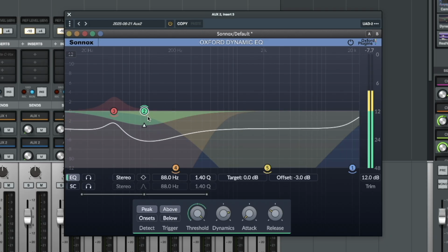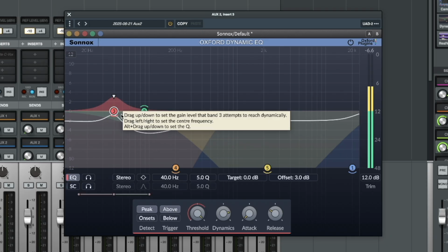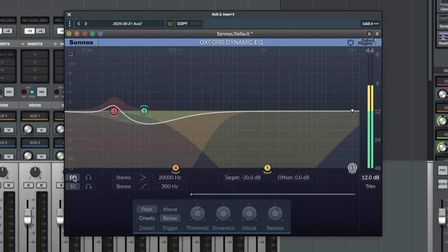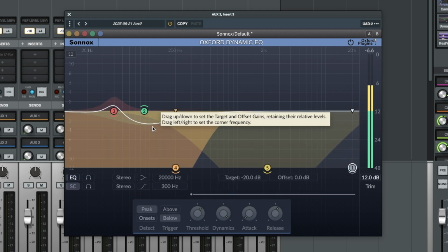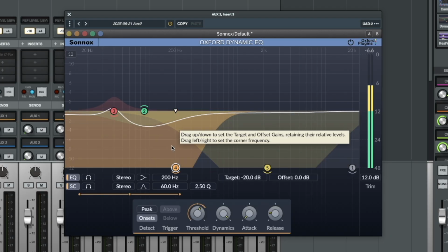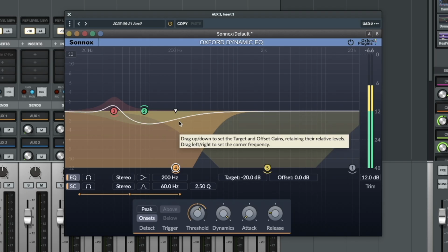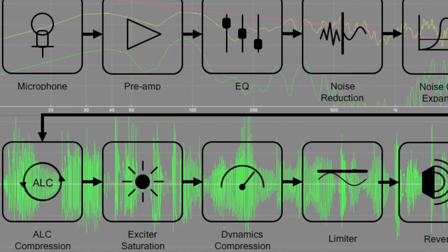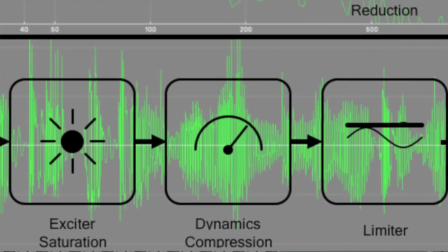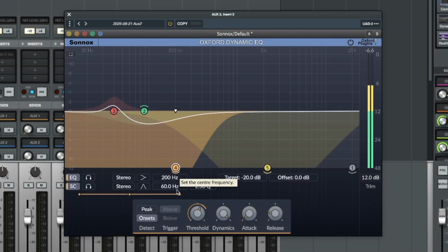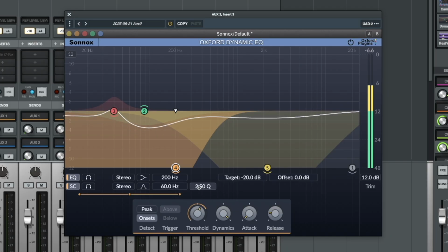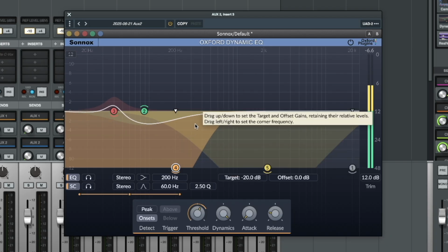Little bit of extra EQ I've decided to put in there. A little bump. Let me turn this off again, actually, so you can see that profile there all the time. And I've got this filter here, which is a de-plosive. Can you see that? So as that bounces down, it's taking some of the plosives out of my audio. I find that detecting plosives at about 60 hertz seems quite efficient. So I've got a narrow filter to do that on the side chain, and it's reducing the audio below 200 Hertz. So that's my de-plosive there.